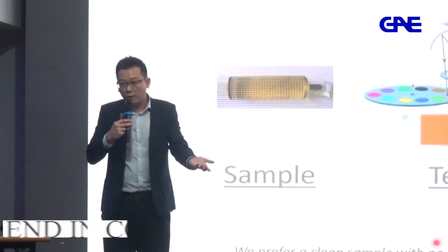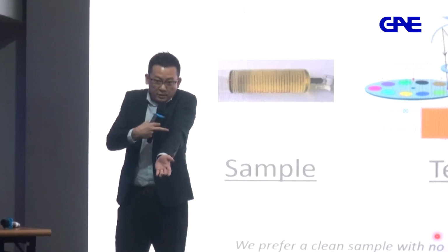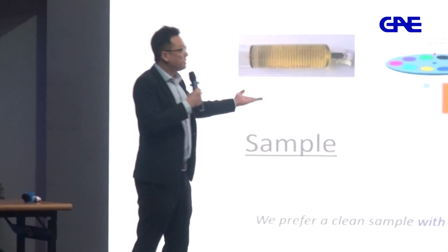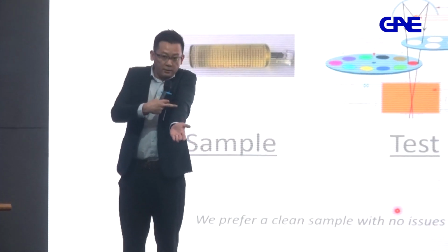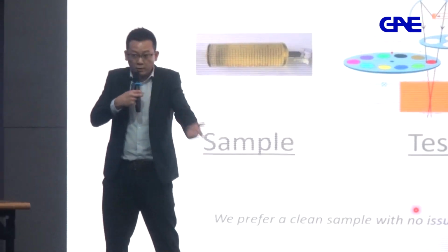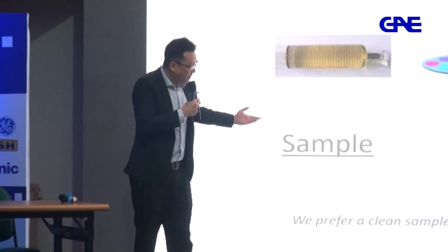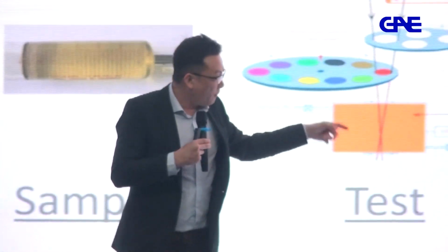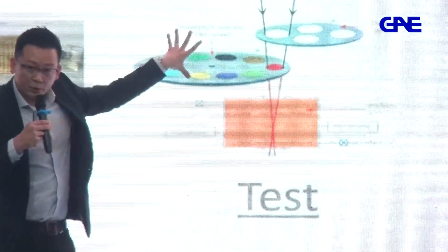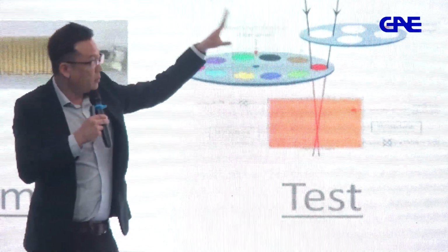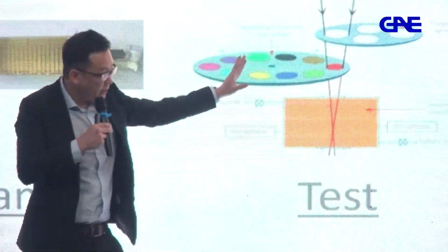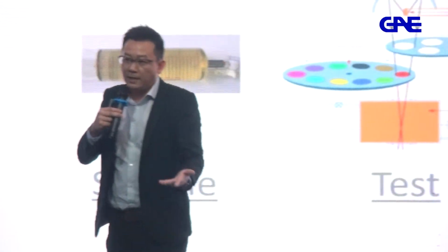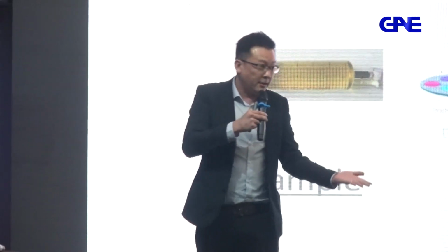Okay, like when you go and draw your blood, the doctor, or even the nurse, will take the blood from your vein. So just imagine that on the transformer itself, the valve is over here, which is your vein. Okay, you draw the oil out, then from there, extract the gas, and from there, put it into the testing position, which what you're seeing over here is a PAS technology. Then from there, we identify what is the hydrogen, the methane, the ethane, ethylene, acetylene, all this.